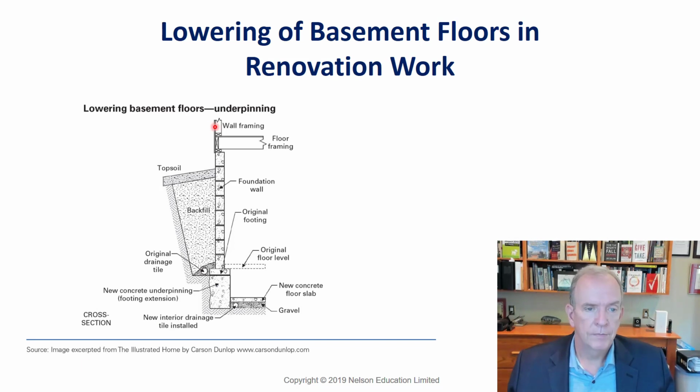So there you sort of see a section detail. So this is actually excavated out. So this is a little bit on the rough side. On the back side, on the smooth side, you'd have the formwork here. And then what's done is a weeping tile is placed around the inside, and there would be a drainage layer that would come down the inside of the wall and underneath. And so that if any water or moisture leaks inside the wall, it would come down and go in the inside. Because you're not damp proofing. With this method, you don't have to excavate the outside. So that saves you a lot of work.